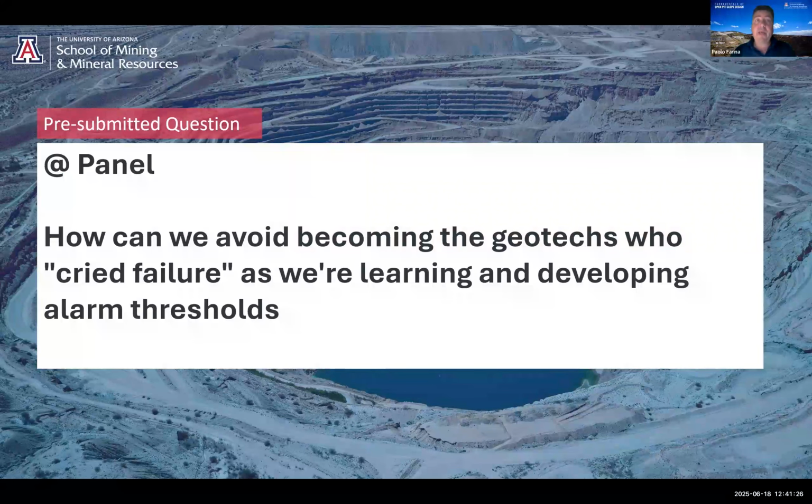And then based on this, we can review the baseline, as Bob said at the beginning, so the noise level of, for example, velocity radar data over a significant amount of time, and define, okay, based on the statistics we got in near range, far range, these are the velocity thresholds, a combination of velocity and time interval to calculate the velocity, and the minimum number of contiguous pixels to activate an area, which could be acceptable in terms of false alarm rate. That's how I typically try to address these issues with my clients.